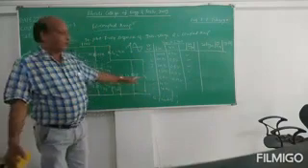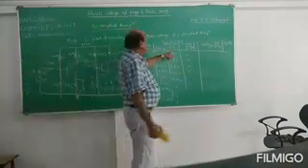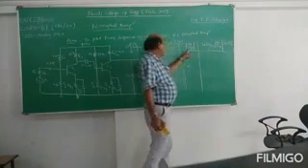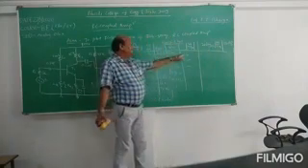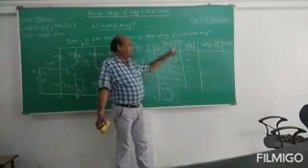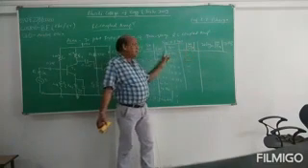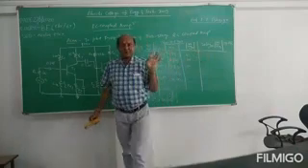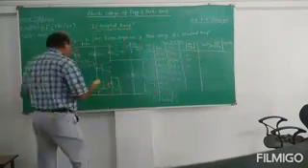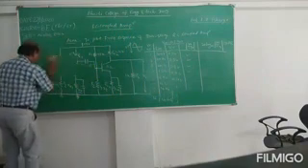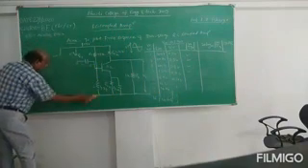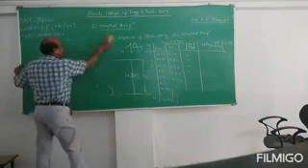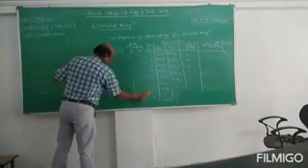Once you have this table and calculation, then you may plot the graph between this gain versus this frequency. For gain versus frequency, you can use the gain as a ratio or you can use the gain in dB, both. So it may be plotted between these two. How this plot will look, I will show you here, the characteristics of this amplifier after getting these readings and after calculation of this table.